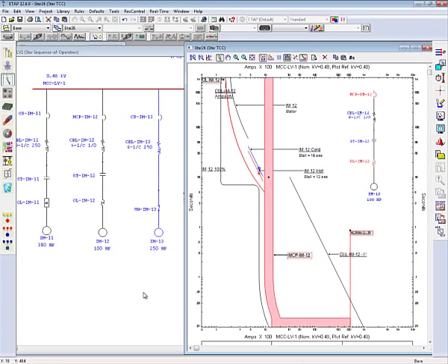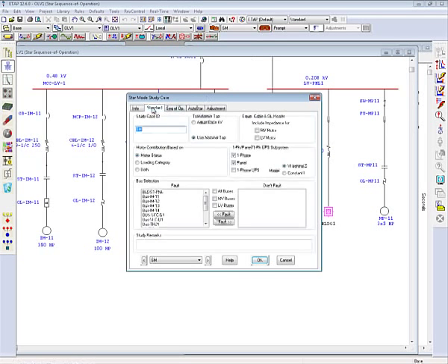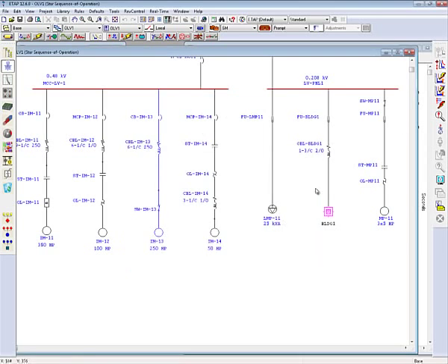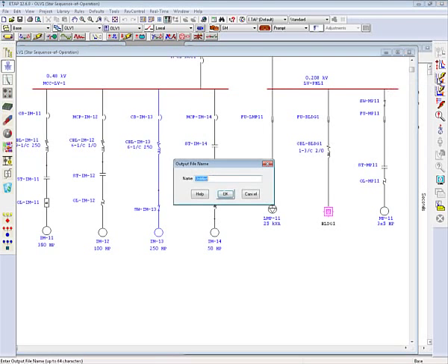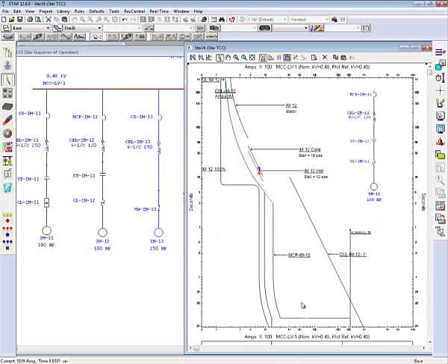So if you are in the star mode and you select to run a new short circuit study, based on the standard selected, the short circuit current type selected, half cycle for maximum current and 30 cycle for the minimum current, and you update the short circuit, you will have your fault markers for the connected protective devices.